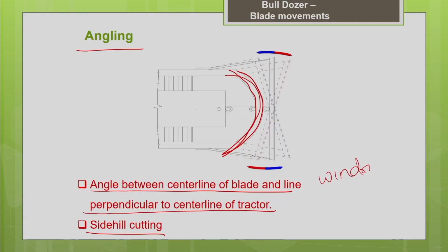So you can just strip the soil and deposit the soil in windrows of soil. So using this angle blade it is very easy to do. But basically angle blades are not considered highly productive blades with respect to earth moving operations. It is not very good in cutting and pushing the earth. I will be discussing that in detail when we discuss the types of blades.